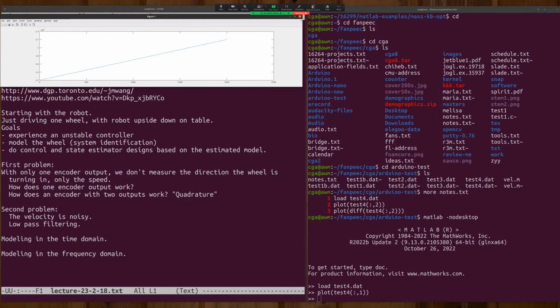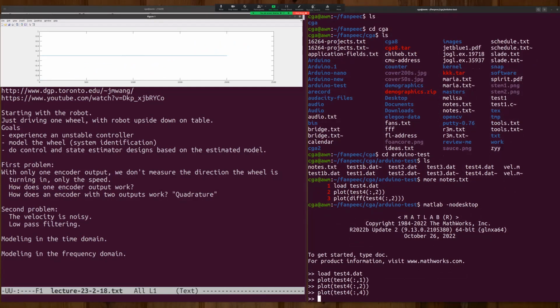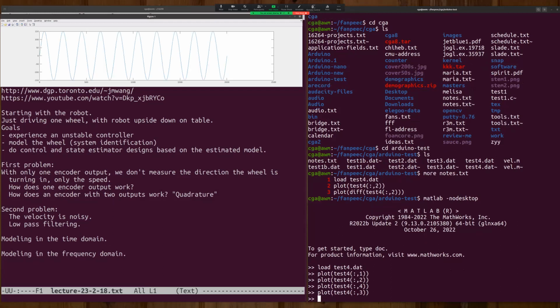And the next thing I do is collect data from the real encoder. And we'll get back to why this looks the way it does in a second. What I'm actually doing while driving this thing is, okay, why did that happen? Wrong number, sorry. I drove the motor with a sinusoidal command, which made the motor wiggle like this.